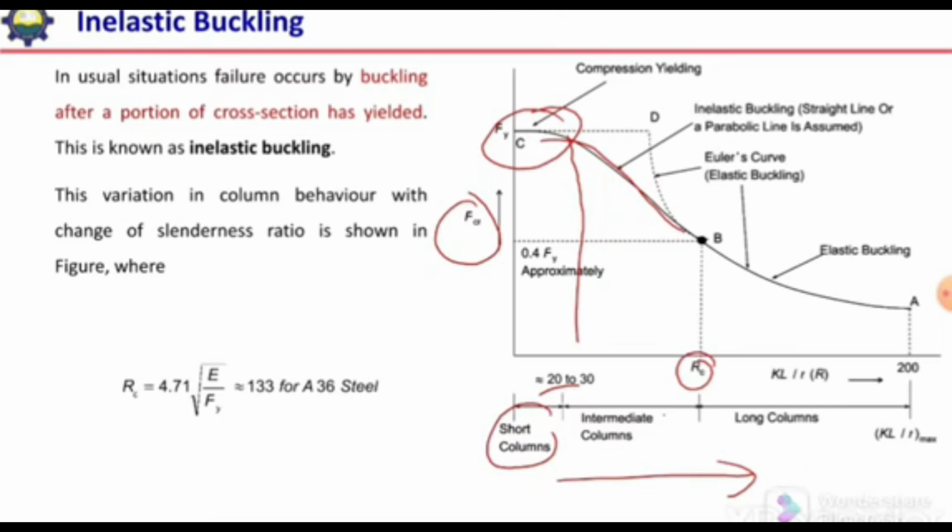If the slenderness ratio is more than this Rc value, we will have elastic buckling. The material will not reach its yield stress at any point. So between Rc and 200 we will have elastic buckling, and between 30 and Rc we will have inelastic buckling, and if the slenderness ratio is less than 30, we will have complete yielding of the section.